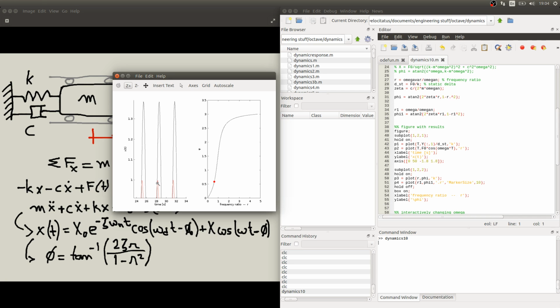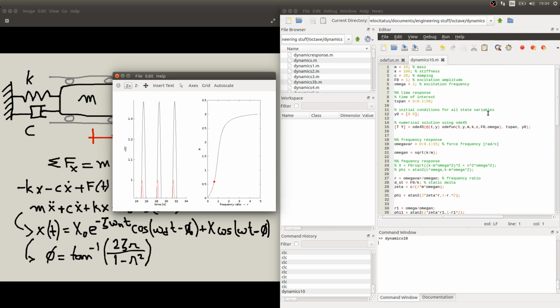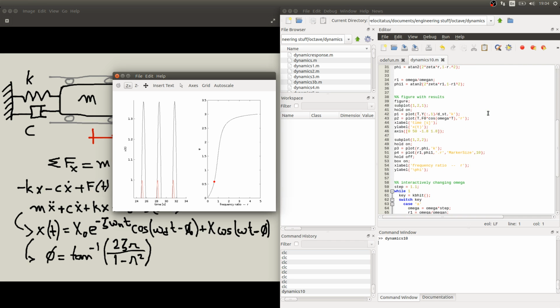And it's called an angle because these two curves are harmonics. So if you look here into the expression for the force, which is the cosine of omega t, this argument here of the cosine can be seen as an angle. So this difference in where these peaks occur can also be shown to be an angle, and that's the phase angle, the difference between where the peak in the displacement and the peak in the force occur.